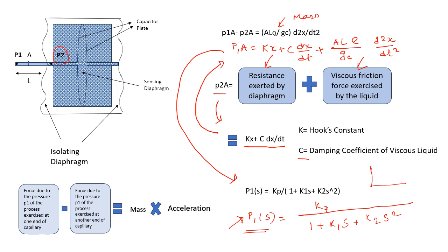This means whenever there is a change in pressure, the displacement of the sensing diaphragm will follow this pattern. And if this pattern is followed, the same will be followed in the current output of the transmitter, right? This can sometimes be difficult to measure, because if it oscillates so much, you will be getting fluctuating readings.